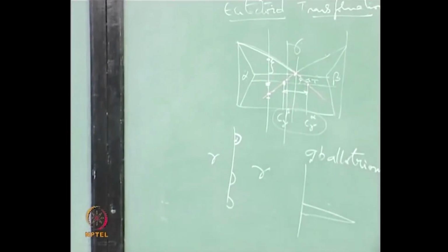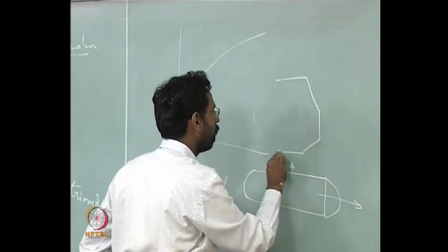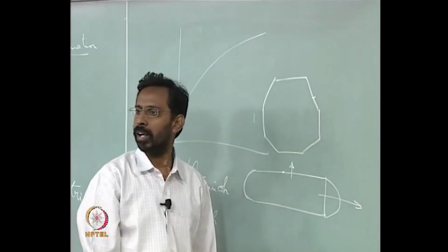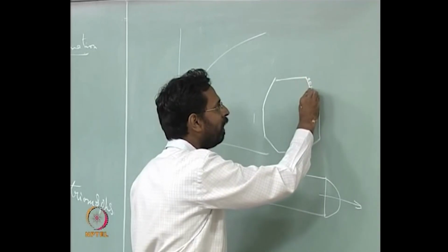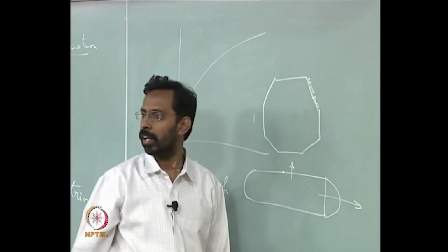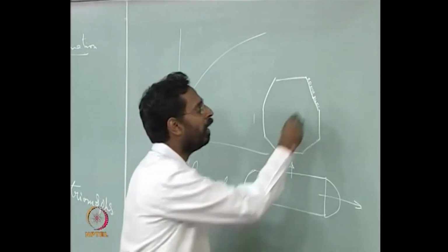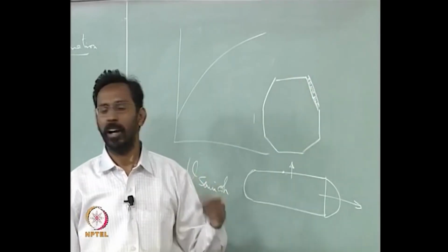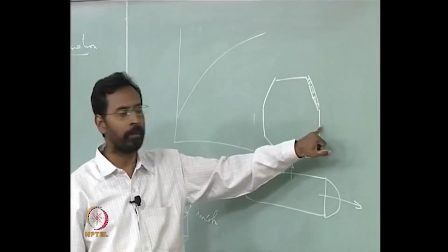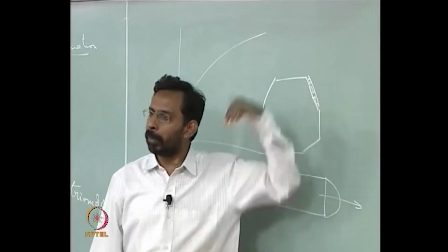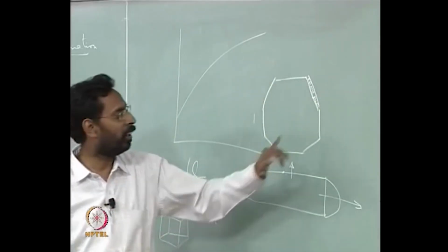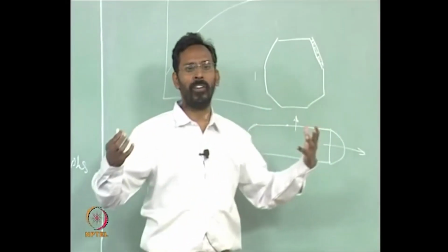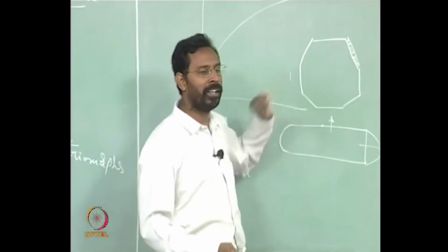because if you have planes like this, something like this, let us say, if this plane needs fewer atoms for it to grow, once all the necessary atoms come and join within a particular unit area, it grows by a small delta x, which is maybe one monolayer. Similarly, if within that particular time the atoms required for this other plane to get completely filled have not reached, then this will not grow, isn't it? So like that you will see the growth morphology sometimes will be entirely different from the nucleus morphology.